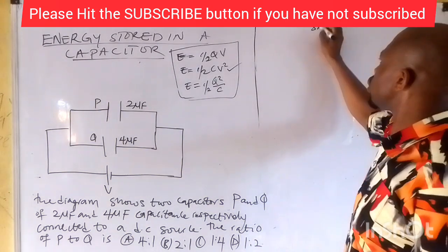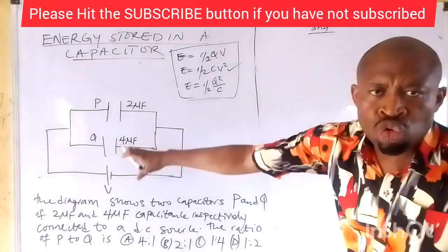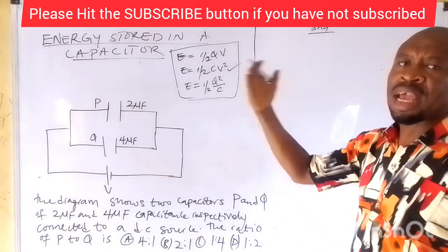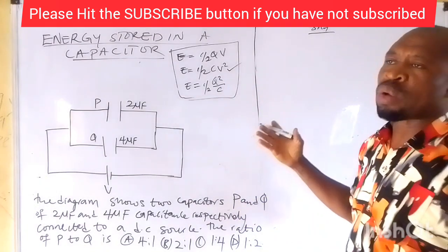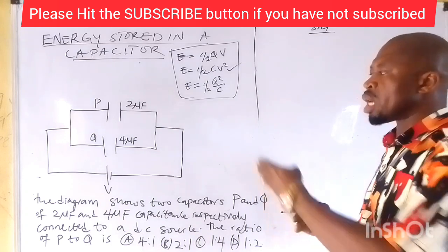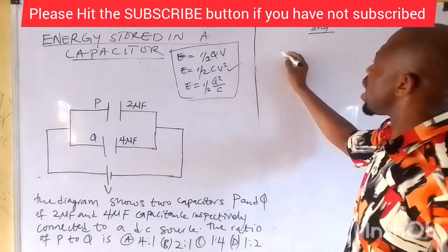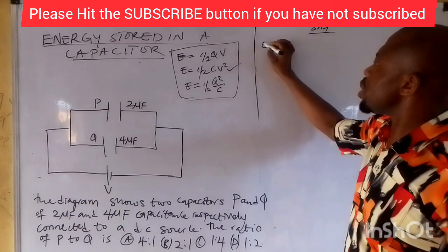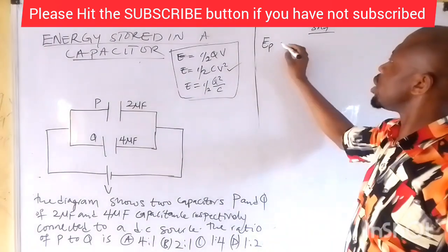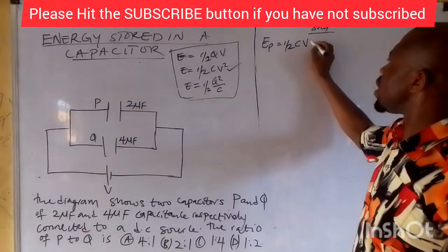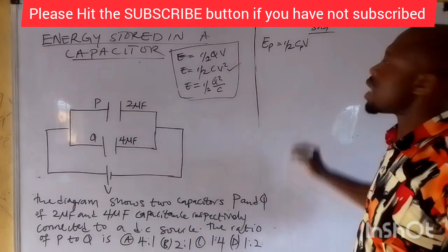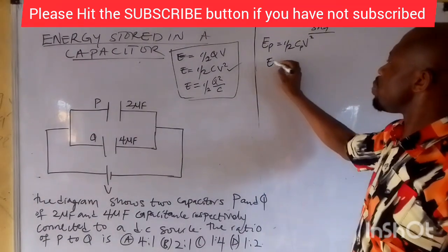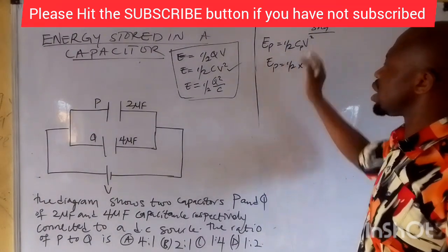Now, solution. There are 2 capacitors there. We'll take the energy stored in each of them, because they do not store energy at the same rate; they store energy according to their capacitances. Energy stored in P is EP, which is half CV squared. So EP is equal to half times CP times V squared.